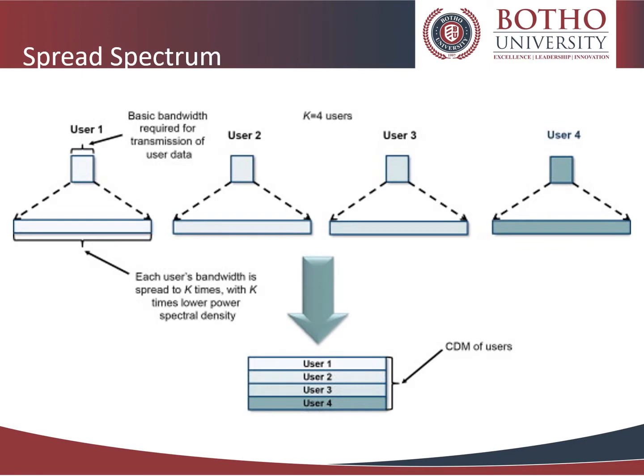Spread spectrum generally makes use of a sequential noise-like signal structure to spread the normally narrow-band information signal over a relatively wide-band radio band of frequencies. The receiver correlates the received signals to retrieve the original information signal. Originally, there were two motivations: either to resist enemy efforts to jam the communications, anti-jam, abbreviated as AJ, or to hide the fact that communication was even taking place, sometimes called LPI, low probability of intercept.